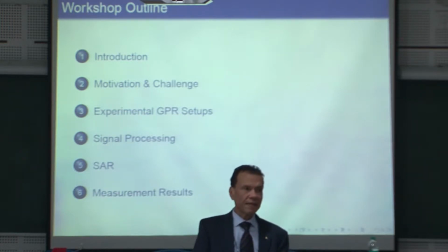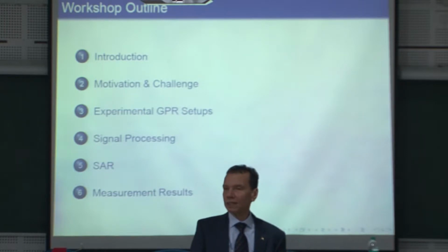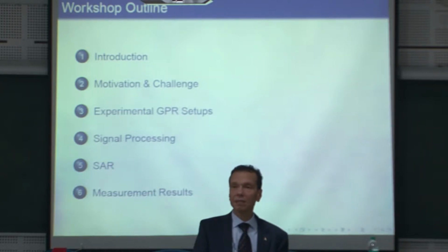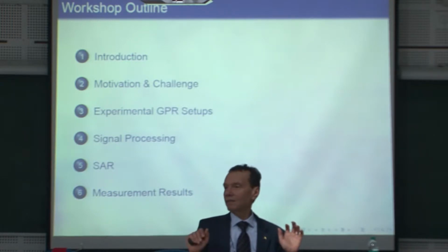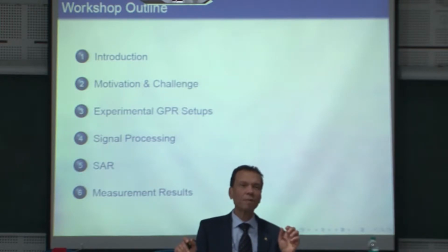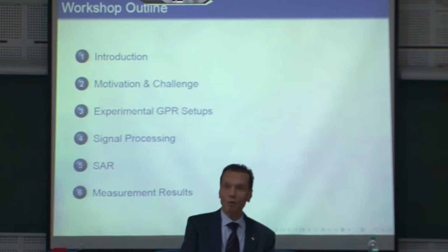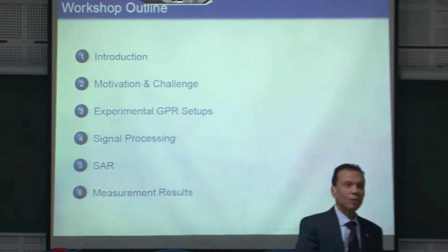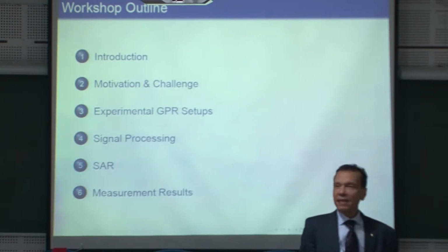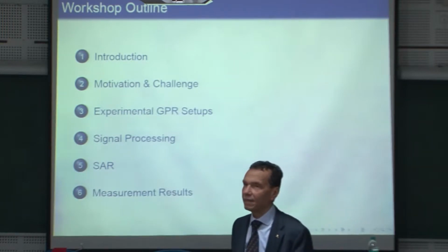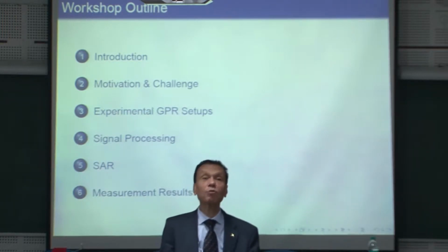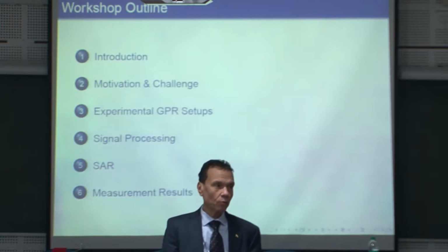And this way of positioning is very inaccurate, because, as you know, in any integration you have an integration constant. And if you have a very, very small error in the first integration, this error is integrated. So at the time you drift. So the cheap way of positioning suffer from lots of problems, and you have to recalibrate and so on.